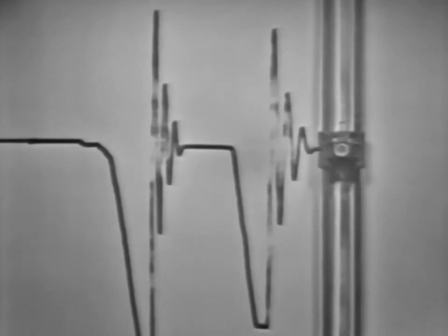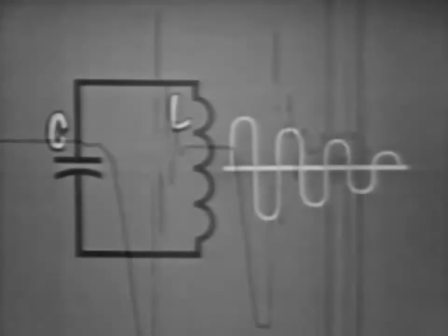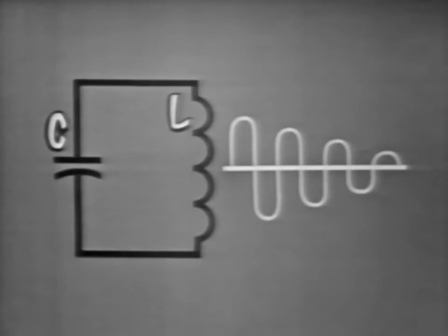Why did the amplitude of the oscillations decrease? In the mechanical oscillator, inherent resistance or friction. Now, if we apply this reasoning to the LC circuit, it's obvious that the decrease in amplitude is caused by internal circuit resistance. That is, the resistance of the wire finally dissipates all of the energy. Now, we'll represent this resistance here.